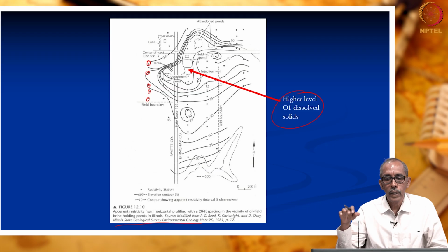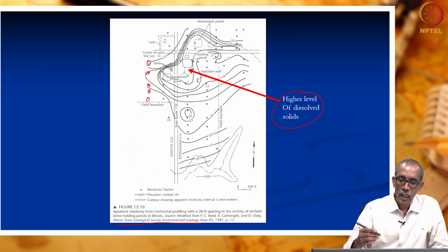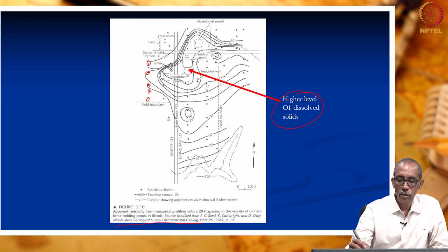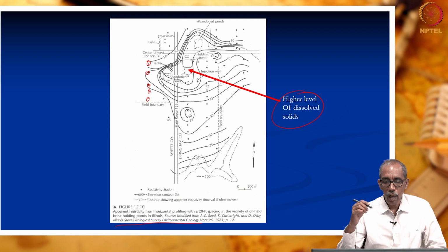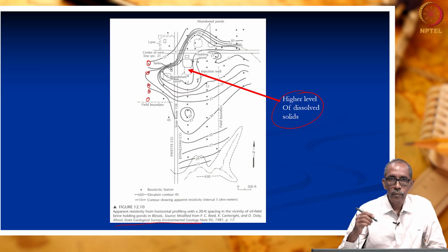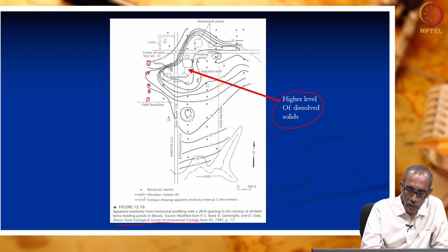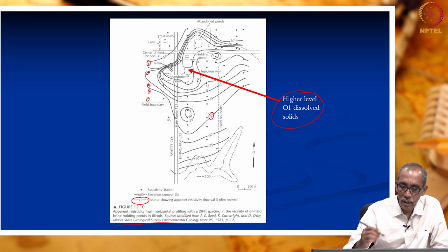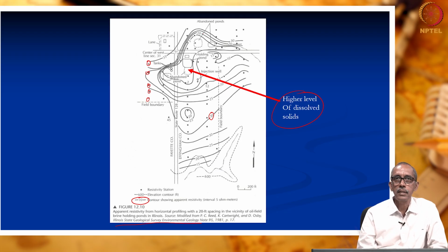After having completed the resistivity survey, all points of equal resistivity values were connected, right. So, we have the contours showing the equal resistivity values, which are all shown in dark lines. All these black lines, this 30 indicates the 30 ohm meter contour level, right.